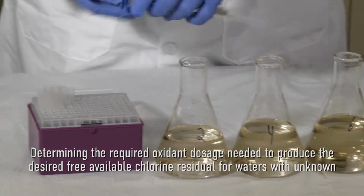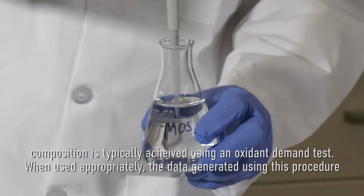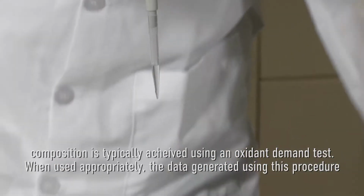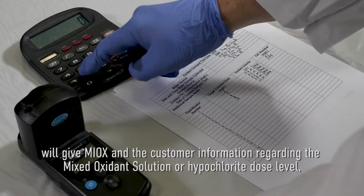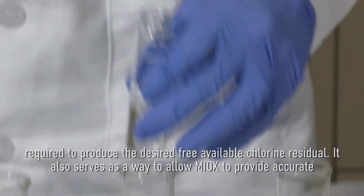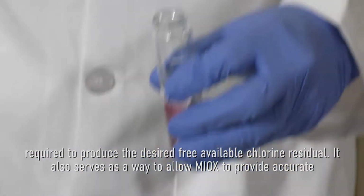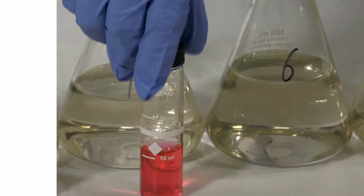Determining the required oxidant dosage needed to produce the desired free available chlorine residual for waters with unknown composition is typically achieved using an oxidant demand test. When used appropriately, the data generated from this procedure will give MIOX and the customer information regarding the mixed oxidant solution or hypochlorite dose level required to produce the desired free chlorine residual. It also serves as a way to allow MIOX to provide accurate information regarding equipment sizing for the desired application.